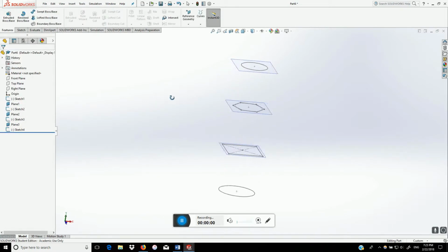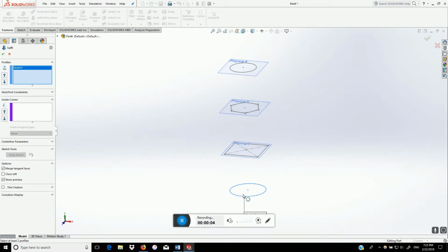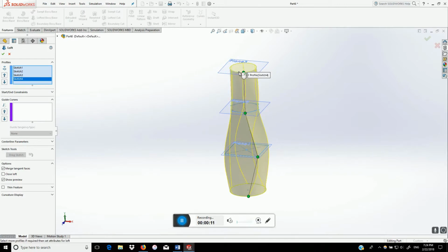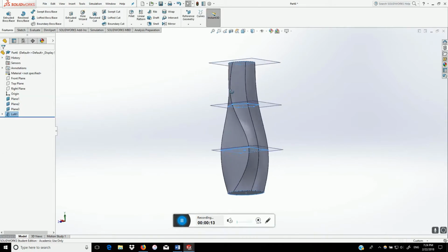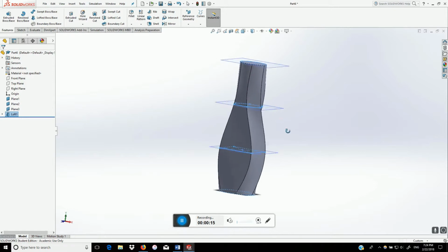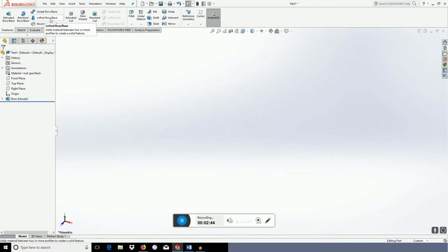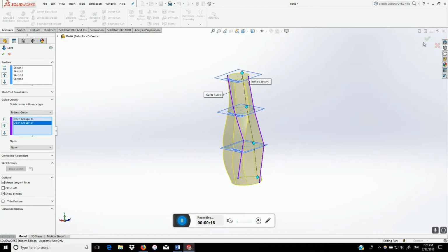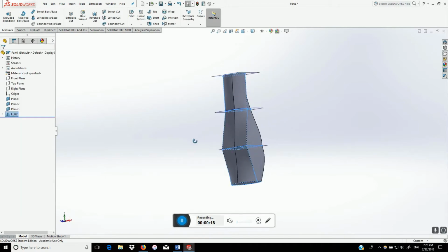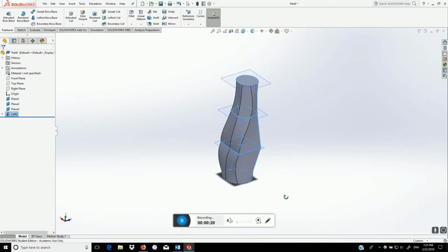If you want to make a belt with your guide curve being a closed loop, just leave those settings as is. Lofted boss bases are used to connect many sketch profiles with one another, sometimes even with guide curves to make the end product more precise. It is usually used when you cannot make something with a revolved boss base because not all features are concentric, or because one or more of the bases is rectangular or not perfectly circular. Thus, it is not often used in shaft design projects. You can use guide curves here as well, and they are most frequently used in this command.